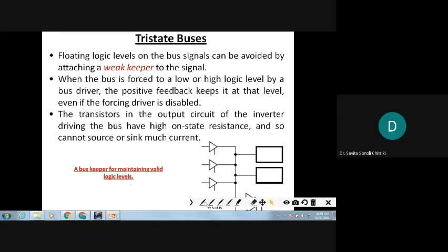See, I will just show you. See what has happened here. Whatever data is there at the input, either 0 or 1, anything on this Tristate buffer. So when a valid enable comes, what happens is the output comes, right? So whether 0 or 1, you are going to get the output which has to reach the destination. But in between, what is happening? The same output line is being connected to what? This weak keeper fellow.